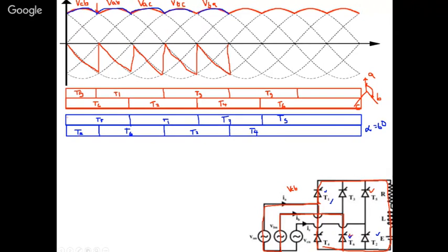So same way 180 degrees. Shift the firing by 180 degrees. In that case, when you see, your voltage will be just opposite to your 0. So A is negative. But we said earlier that the thyristor is unidirectional, the current can go in only one direction. Then how will it come back to the supply power source?